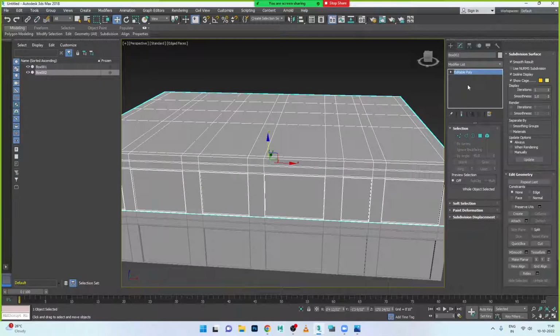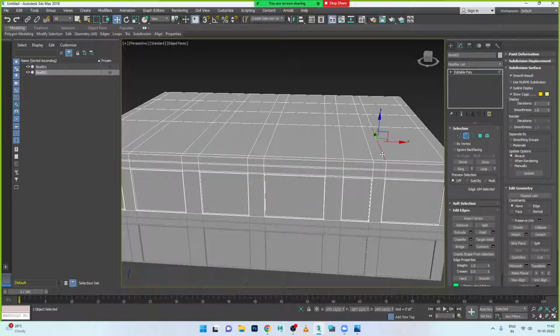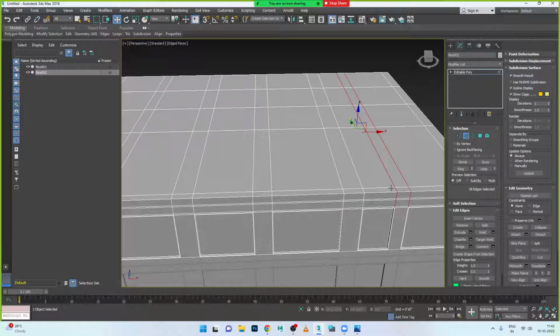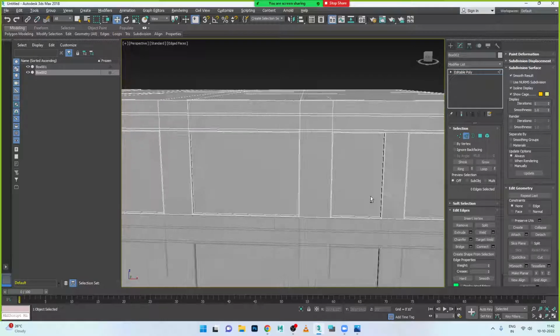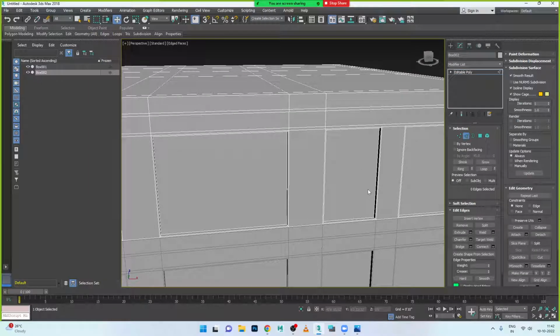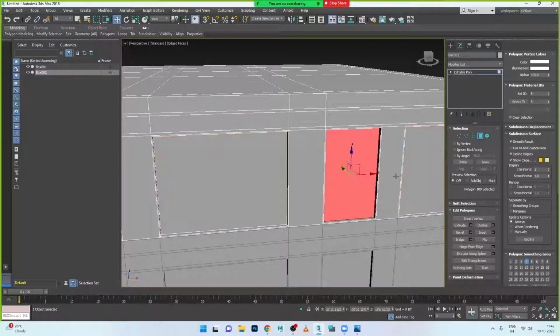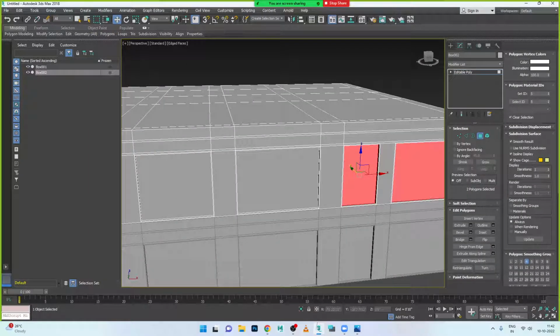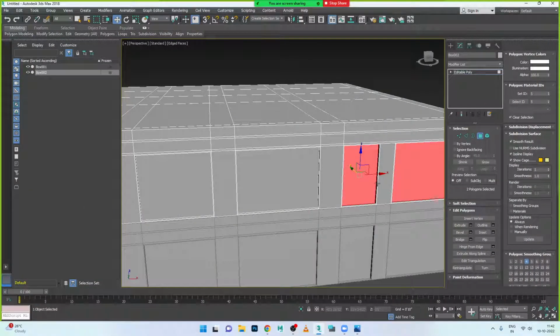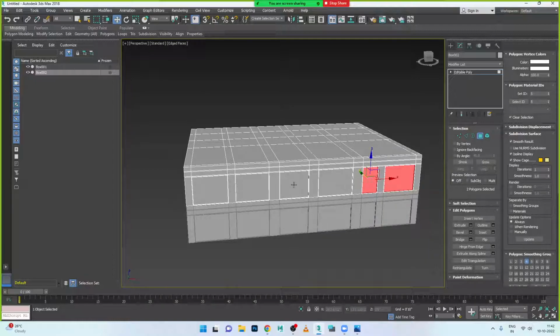So select this one, go to the edges, double click on this edge, double click on this edge. Okay, and use control backspace to delete these edges now. Okay, now similarly this side also. Okay, we have some depth in this one. What I'll do, I'll select these faces. One second, let me see. These two partitions we need at last. Otherwise I'll do one thing.